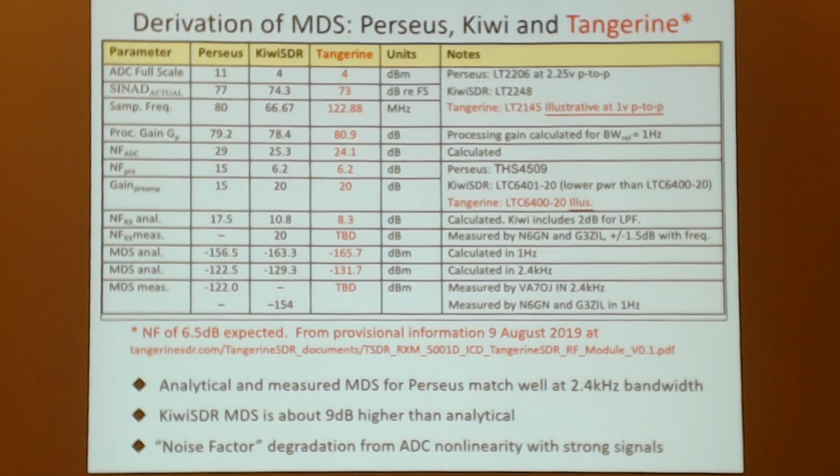And it was originally masking the background noise that we were getting from the antenna system at KPH. So I addressed this, as I think may be needed at many receive sites, by putting an external preamplifier ahead of the Kiwis. It turns out what I added was 23 dB of gain, the DX Engineering implementation of the Clifton amplifier, which uses these Gali-73s.